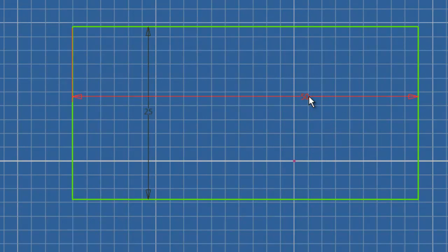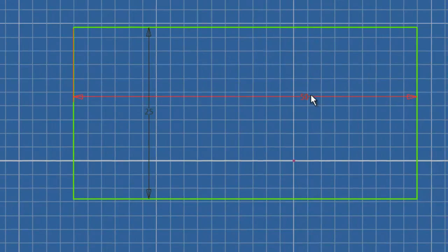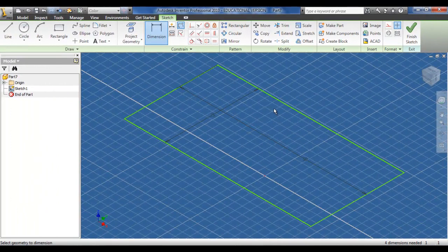Another interesting point here as well is the fact that all measurements in Inventor can be selected to a default setting on download. So for this tutorial and all following ones, my measurements will be based on millimeters. What you actually saw there as well was the sketch plane flattening out. That is carried out by pressing the F5 key on the keyboard. Basically this makes it very easy to see when we're extruding from 2D to 3D.